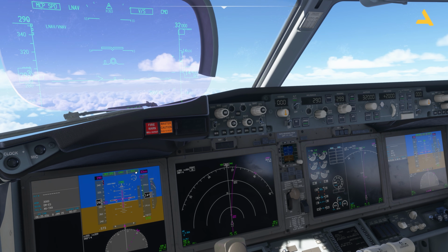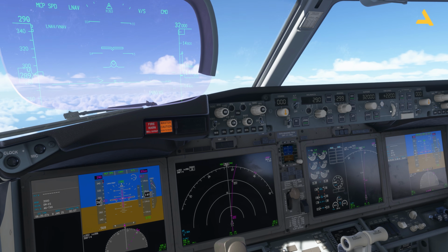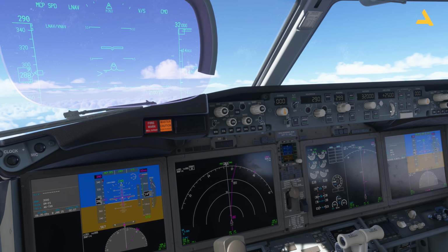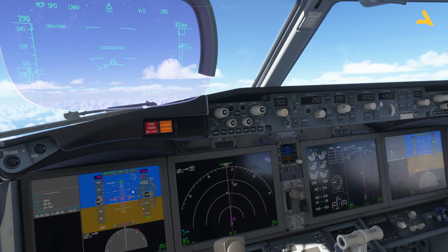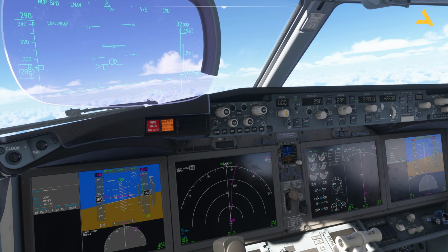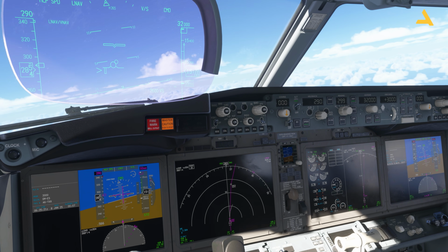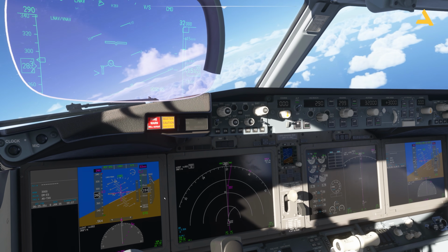and the vertical speed is now appearing over here, which shows you that the plane is in the vertical speed mode. So whatever vertical speed I set, the plane will follow it. But remember this thing, that in this mode, the vertical speed is the priority and the speed is not. So let's say if I go up to 3000 feet per minute, you can see the speed is reducing because the priority is the vertical speed.